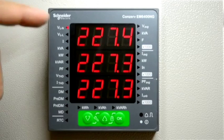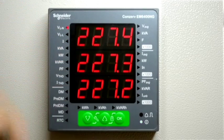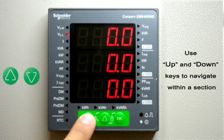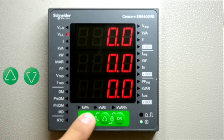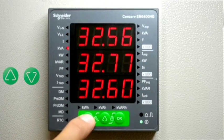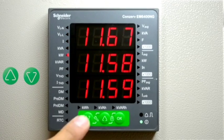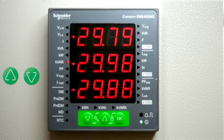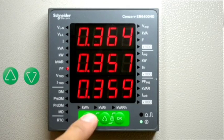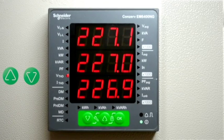This is the RMS section. Now the meter is showing voltage line to neutral of individual phases. Press the down key to view voltage line to line of individual phases. Similarly, current of individual phases, per phase kVA, per phase kW, per phase kVAR, per phase PF, VTHD and ITHD values can be viewed.